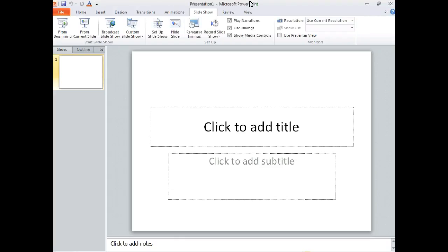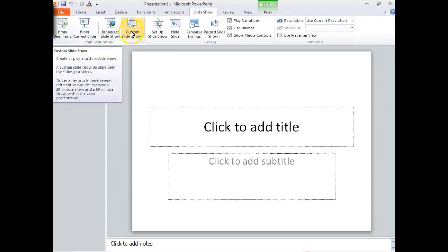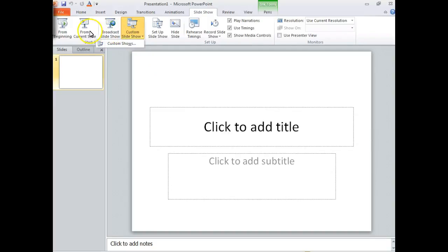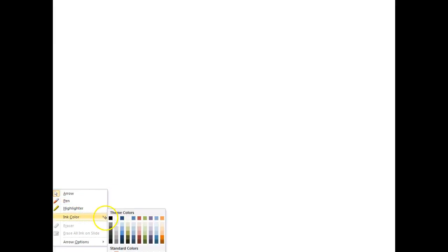So if you could think of a multiplexer as being a switch, and what I've got is all these inputs. How many inputs do I have? I'm not going to draw all 8 of them, but let's say we have a 3-input multiplexer. I bring these in, so this would be N0. This right here might be N1. This might be here N2. And then I've got a switch over here that has the Y output.